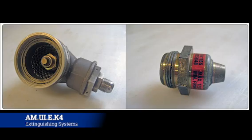So as maintainers, it's something to remember. If they've pulled the fire handle, it's very likely that all the fuel valves are closed, so that way the plane can compartmentalize the fuel and keep the fire from spreading. And this can happen. People can do it on accident, and you might even swap out the engine. Then you can't get the thing to run. You're wondering why. It's like, oh, you forgot to go back and check all the fuel valves and open them up. Speaking from experience, but that is how the bottle works and how it discharges. And there's not really that much more to it. This is kind of like your one shot wonder to put that fire out.